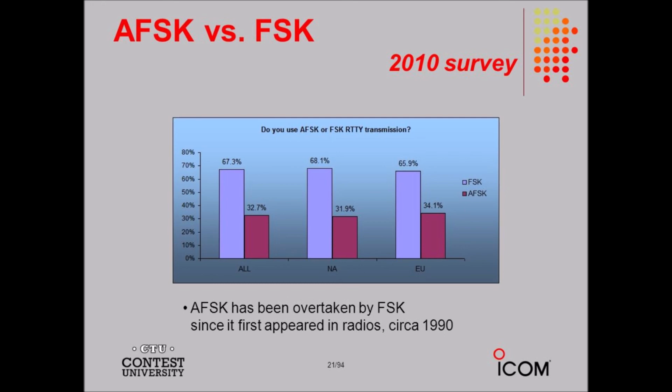The deviation in the final output should equal the highest modulating audio frequency if we expect optimum audio fidelity. Therefore, plus or minus 5 kHz is more than enough deviation for voice communications. For music, a deviation of plus or minus 15 kHz or plus or minus 20 kHz is required for good reproduction.